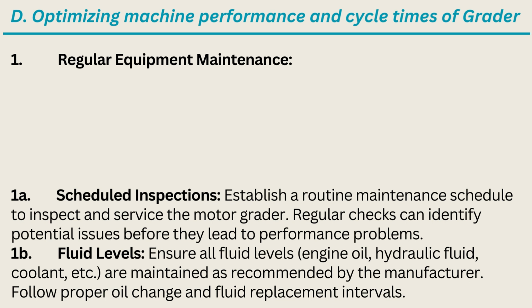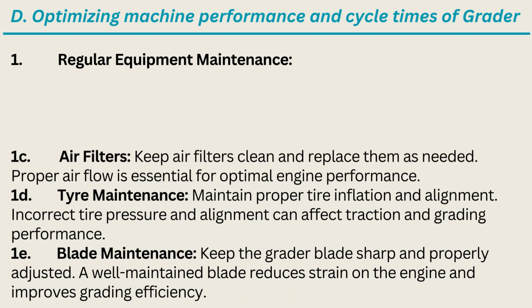1B. Fluid levels. Ensure all fluid levels, engine oil, hydraulic fluid, coolant, etc., are maintained as recommended by the manufacturer. Follow proper oil change and fluid replacement intervals. 1C. Air filters. Keep air filters clean and replace them as needed. Proper airflow is essential for optimal engine performance.